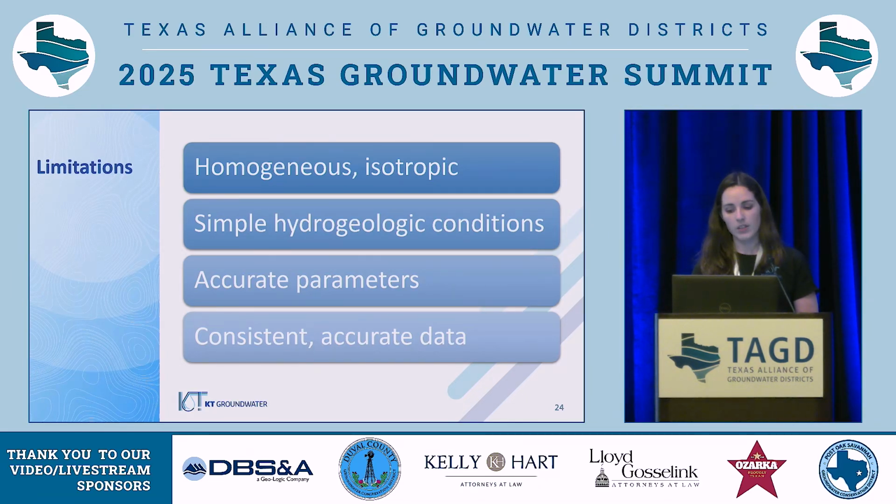If your transmissivity and storativity values are coming from the GAM, those are not considered data because they're just estimates. If you had transmissivity and storativity values from pumping tests, these would be much more site-specific, so that's definitely preferable. For slope calculations, slope regression ignores outliers, so it may not capture a non-linear trend. It's also important to have, again, high-quality, consistent data.